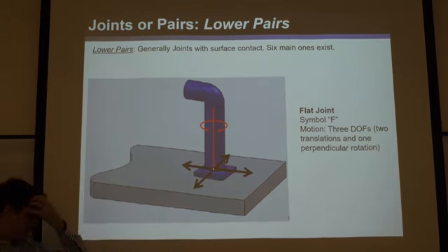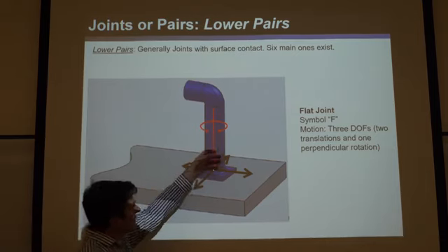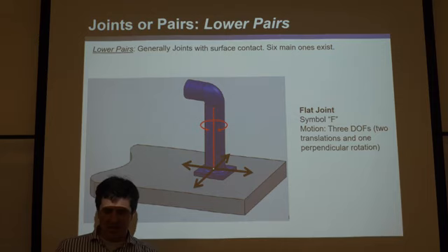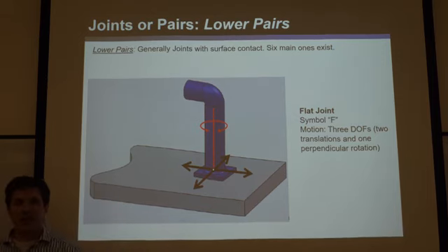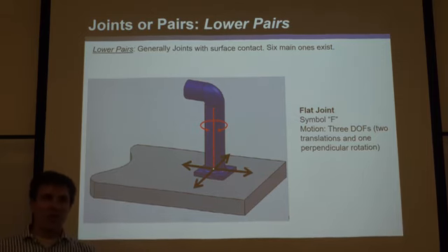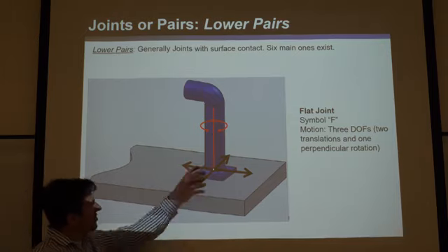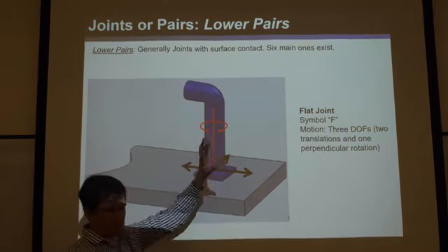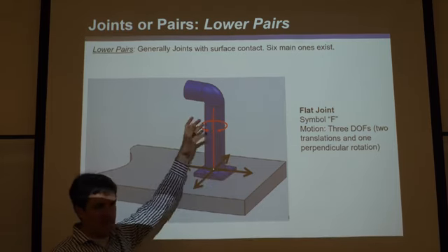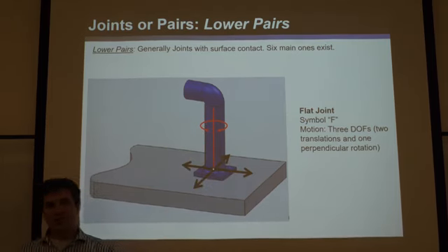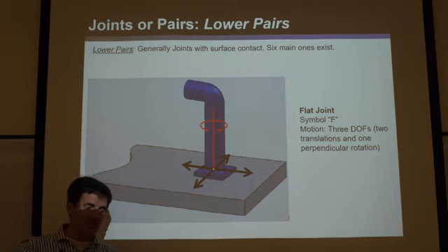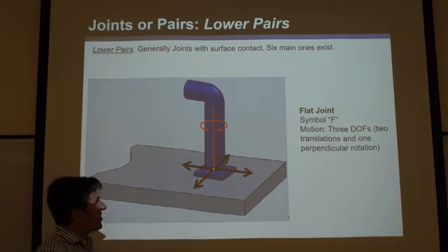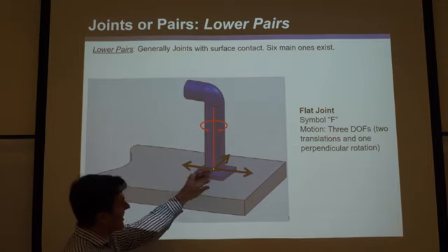Now you might say, well, my goodness, I could just lift this right off, and you'd be right, but you would break the joint. And that's a rule that I want to ingrain in your mind: you can't break joints. Not only can they not go through each other, obviously, but you can't lift it off. Of course, in the physical world, you could lift it off, but you're not allowed to. Once you separate the 2 links, it's no longer a joint. So when you're analyzing its degrees of freedom, you have to assume it can't be broken.